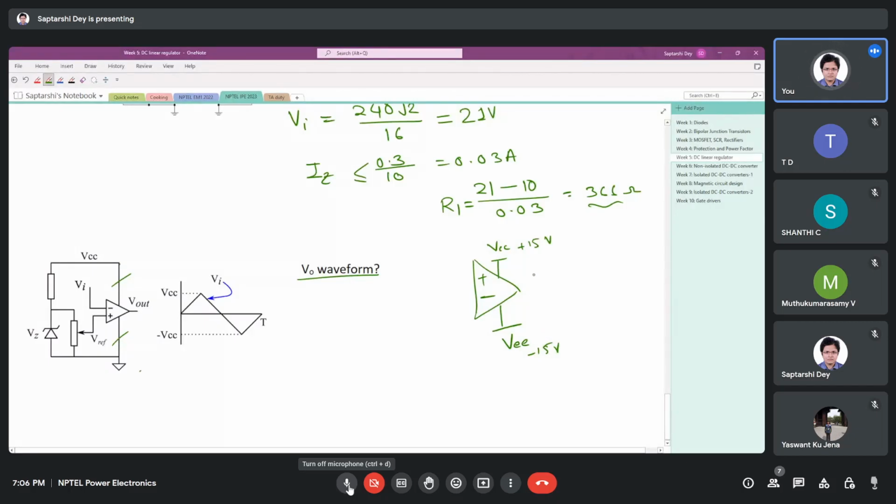So this is understood at least from the power supply and the circuit. Sir, excuse me, on the negative side you said saturated at zero? Yes, because it is grounded. So this is not the case here, it is 0 volt. So it's a comparator circuit and the supply is 15, VCC and 0. So the output will switch between VCC and 0, no other state.